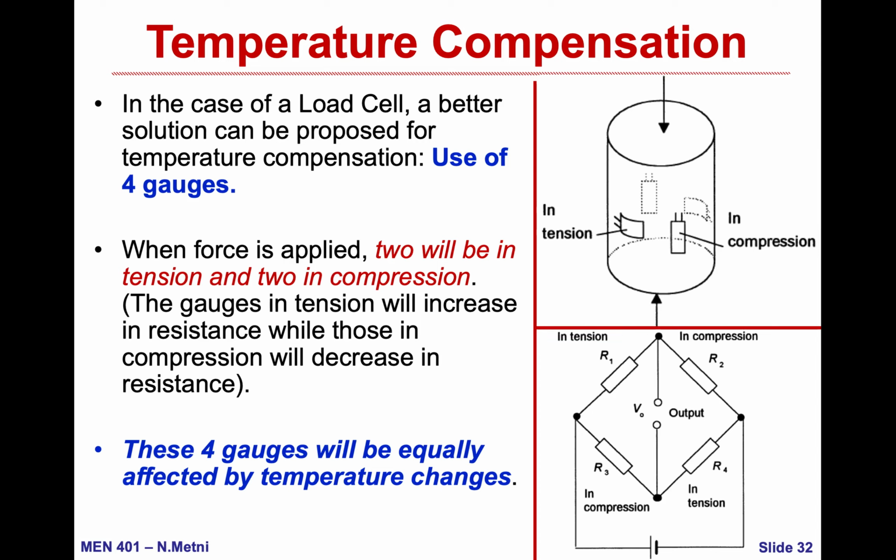This is one of the biggest advantages of the Wheatstone bridge, because it takes into it the temperature compensation by not only having one leg being the resistance, I can have another leg being a dummy gauge, or in other cases, one in tension, one in compression, and I can use the four legs of the Wheatstone bridge in this way. This can be useful for temperature compensation, and by using four of these gauges, the sensitivity of the bridge will be increased. Therefore, for a small strain, I am seeing a large delta V.